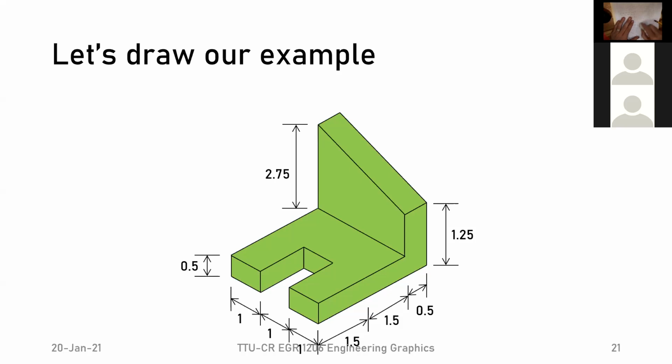Dr. Bandela, why did you draw the diagonal lines in from the beginning, like the construction lines? Why are they necessary? Yeah. They are not entirely necessary. They're kind of helpful at the beginning. So they help you to place the right side view in accordance with the other one.